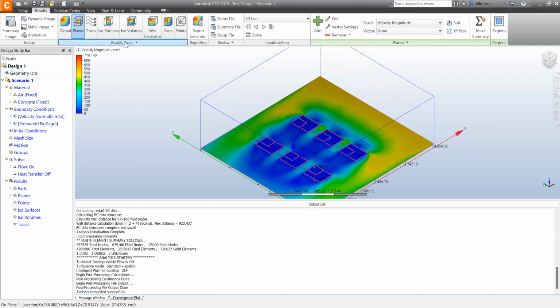And the last one is the legend of how much the velocity is. It's still on cm per second. We have to change it. To change, just click the legenda, right click, and then option, or maybe the unit you could directly from here change into meters per second. Nah, so it's from 0 to 7.